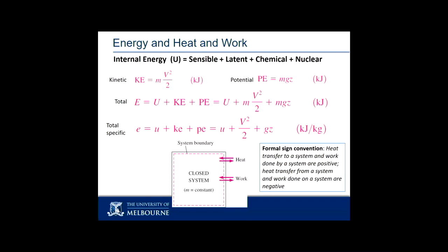This thing is up there because it's in all the thermo textbooks. And so if you're reading a thermo textbook and you see positive work, it means work came out of the system. It means the system energy has gone down. If you see positive heat transfer, it means the system energy has gone up. So it's worth knowing, even though mathematically I get scared of making assumptions like that and I try to keep track of all the minuses and pluses.